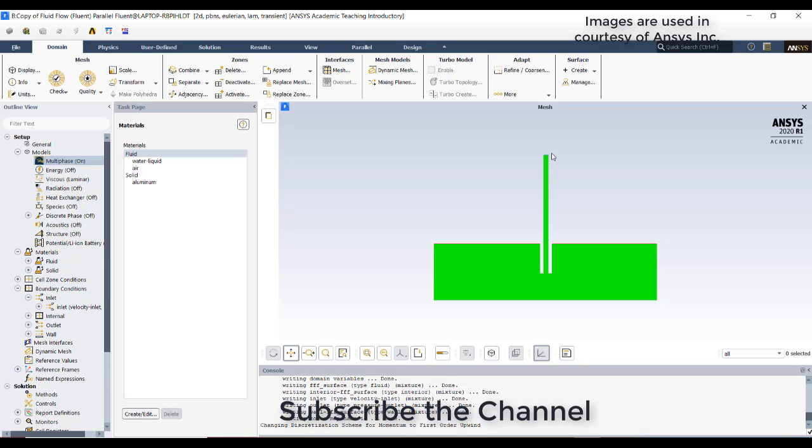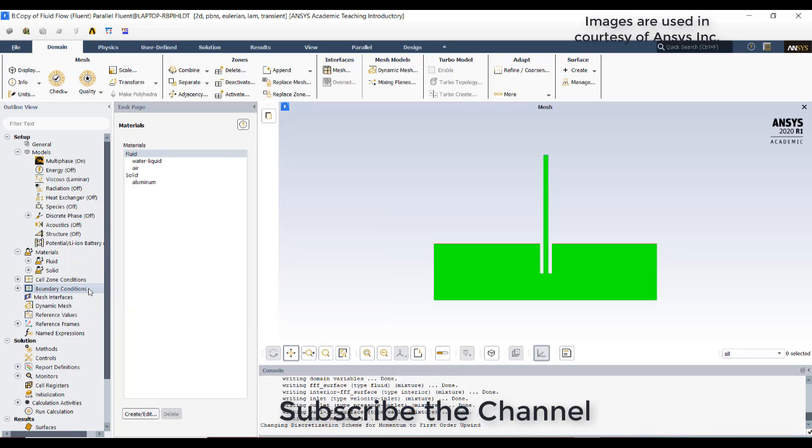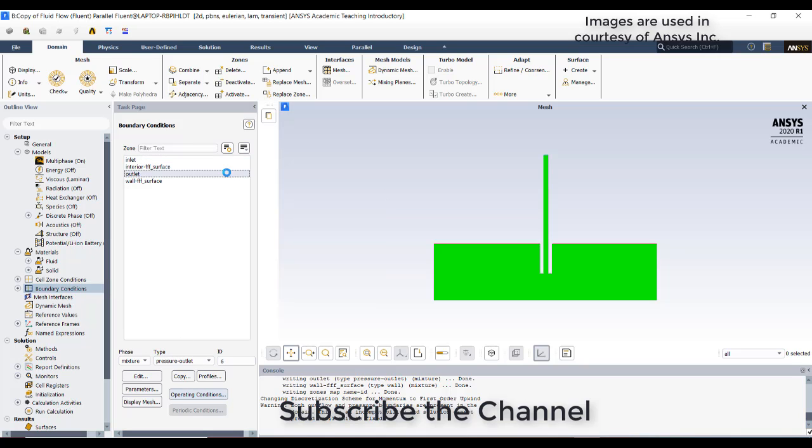So inlet, there is no inlet here. I have named this point as inlet, but that inlet is nothing but an outflow condition. You can give an outflow condition. So go to boundary conditions. Inlet is nothing but outflow. The outlets are these red lines you can see, right? This side and this side are also outlets only, with the outflow condition. Outflow,